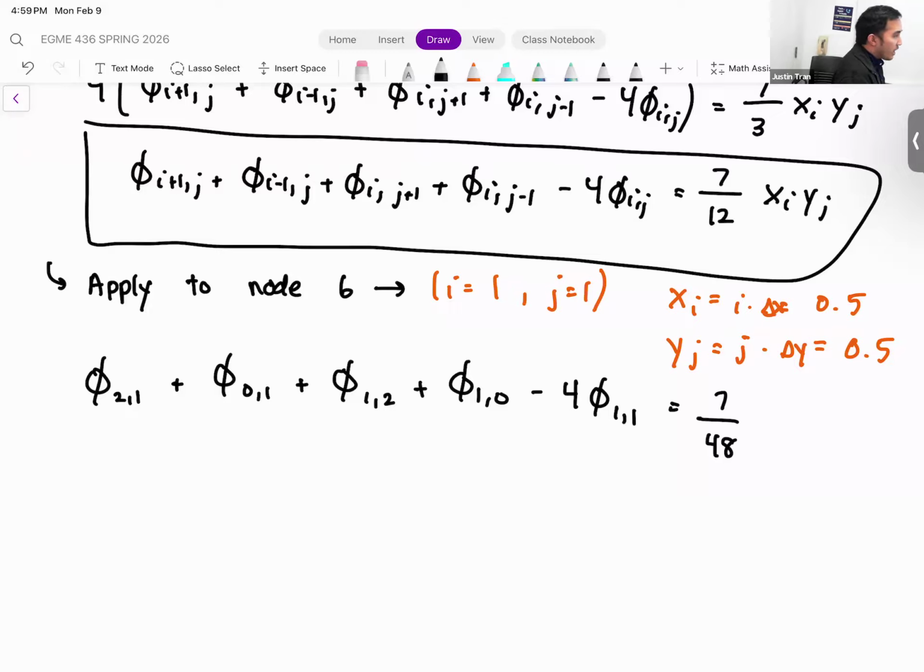And so from here, you can take every single ij coordinate in here and plug it into your ID equation, and then get your ID numbers for each of these nodes. That's one way you can do it. But for these simple problems, and because we're not going to be doing the programming, I would say just go visually off the grid. Because we know that I plus 1 comma j is our right neighbor, I minus 1 comma j is our left neighbor, j plus 1 is top, and j minus 1 is bottom.